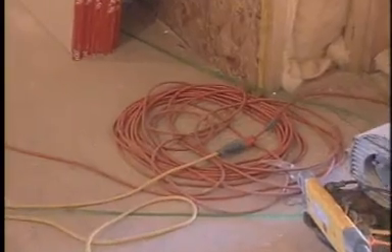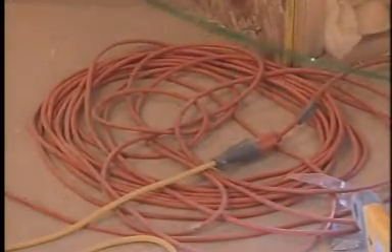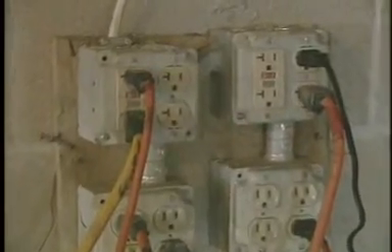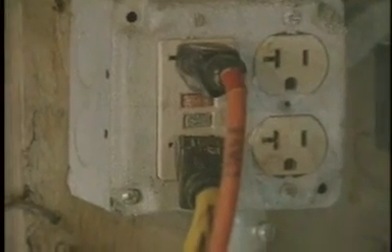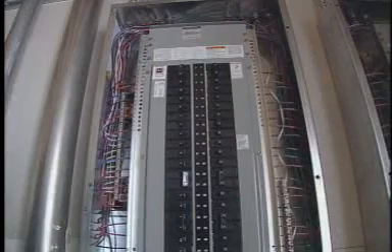To avoid accidents, your first protection is to make sure your electricity is properly grounded. This means creating a safe path for it, away from your body, and containing it within the equipment or tool you're using. Fuses and circuit breakers help protect cords and equipment, while ground fault circuit interrupters, or GFCIs, protect people. GFCIs are required on all temporary power at construction job sites. Fuses, circuit breakers, and GFCIs should be checked regularly.